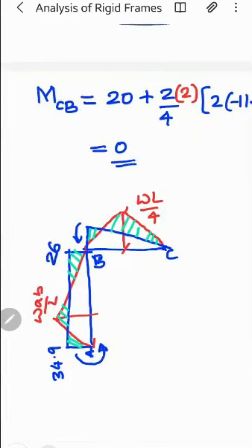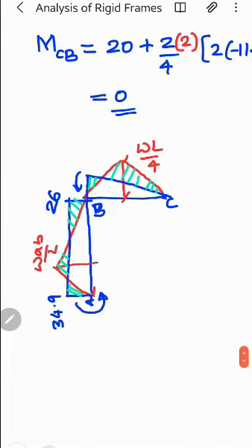This is how we can draw the bending moment diagram. Clear? What you need to do is take only the member which you want to draw. Take member AB separately, and get the moment value, whether it is clockwise or anti-clockwise. See whether the member with that couple deflects upward, downward, or left, right, and accordingly draw the ordinate either to the left or right side or upward or downward. Similarly for the other end, do the same thing and join this. So you'll get the fixed bending moment diagram, and the earlier one drawn is the free bending moment diagram. Clear? So this is the final bending moment diagram.